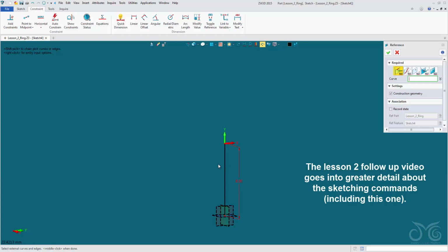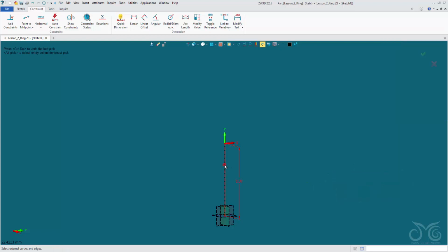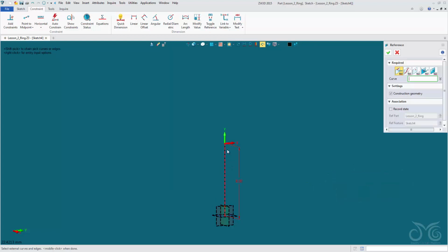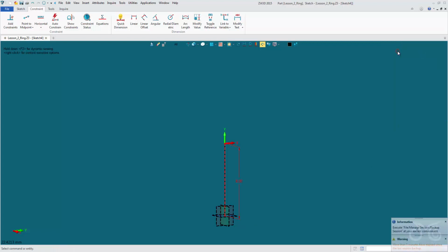And now you'll see I can select the curve or the sketch that we created previously. If we left click, it will input a red dashed line. Here we exit this now. And then when we come to show target again, the 3D environment is hidden, but we now have our reference from that environment, and it stays in our 2D environment.